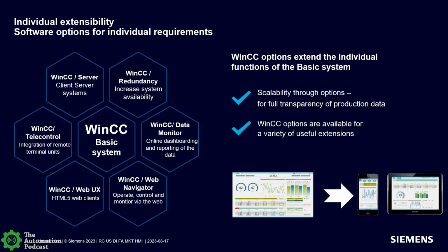With a lot of HTML5 web-based clients now out there, and trying to get a lot more communication capabilities or spread the information around to cell phones and other non-Microsoft applications, a few years ago we came up with WinCC Web UX, which is web user experience. And that does a similar thing. It allows any HTML5 device out there to open up a web browser and get access to the WinCC server and be a client that way.